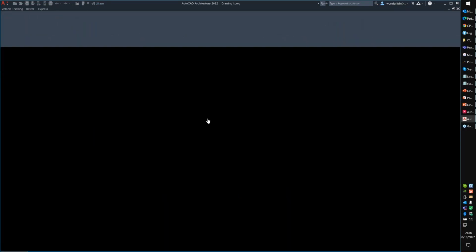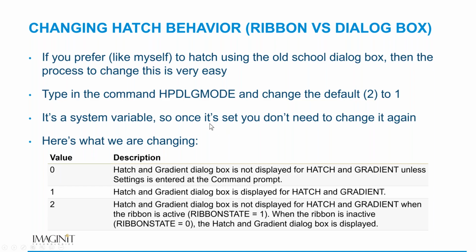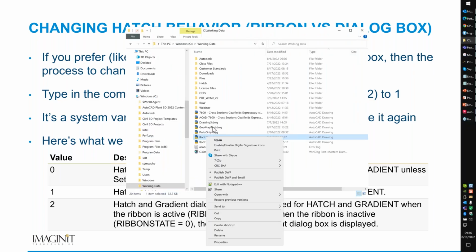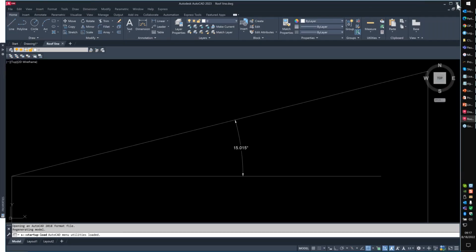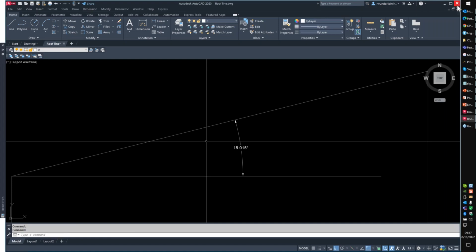That is exactly the same for TrueView as well, Robert. So if you are set to use the AutoCAD DWG launcher and you have DWG TrueView and you open up TrueView last, so that's the last product that you open, it will immediately default to TrueView when you just double click on a DWG. So I'm just going to open this, and what it should do is it's going to bring me to here because I actually opened this after, because this is what I actually had opened.